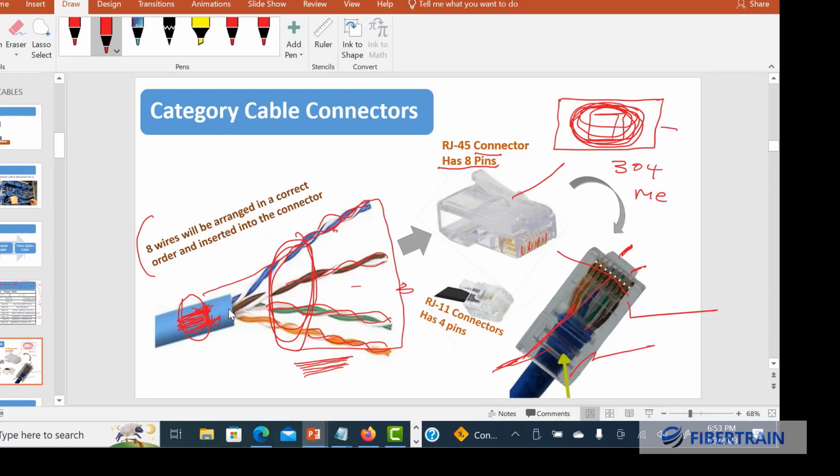Yes, absolutely. So in a building, in the first floor, we need to map out where our switch will be located, and we now need to know where the staff are to be seated, and we need to have a measurement of what it takes for this particular staff to get connected to where the switch is in the same floor. And we'll add up all this per floor, and we'll be able to know, oh, maybe we'll be needing 12,000 meters of cables to network the entire building. And we already know that one pack will give us 304. And so we can do the math and come up with how many cartons in total we'll be purchasing for that company.